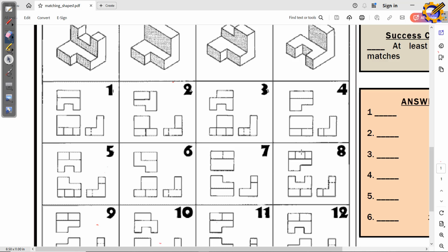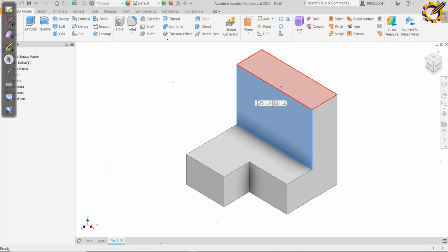I can draw it on this area on my plan. That is, I can draw those two lines somewhere here like this. Then I can draw it here, 1, 2. That's one way. Or I can draw it on the front, 1, 2, 3, then extrude it backward. Now if I generate it on the plan, I will be cutting inward, downward in this direction. But if I draw it on this front, I will be cutting through like this. I will be cutting this shape through so that I can have that space. So your choice. But let us generate it on the front.